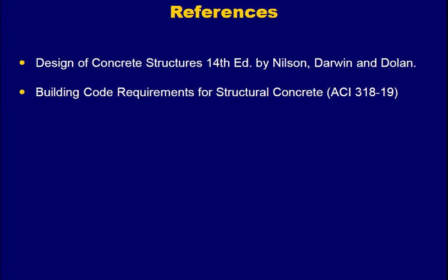And if you are asking about the L-beam, there is nothing to worry about. It is similar to the T-beam, you just have to consider one side of the slab, and the equations that I already provided on the slide are to be used for the calculation of bf. On the basis of that, the rest is similar to the T-beam. So no worry about the difference. The only difference is that the T-beam has slab on both sides and the L-beam has it on one side.